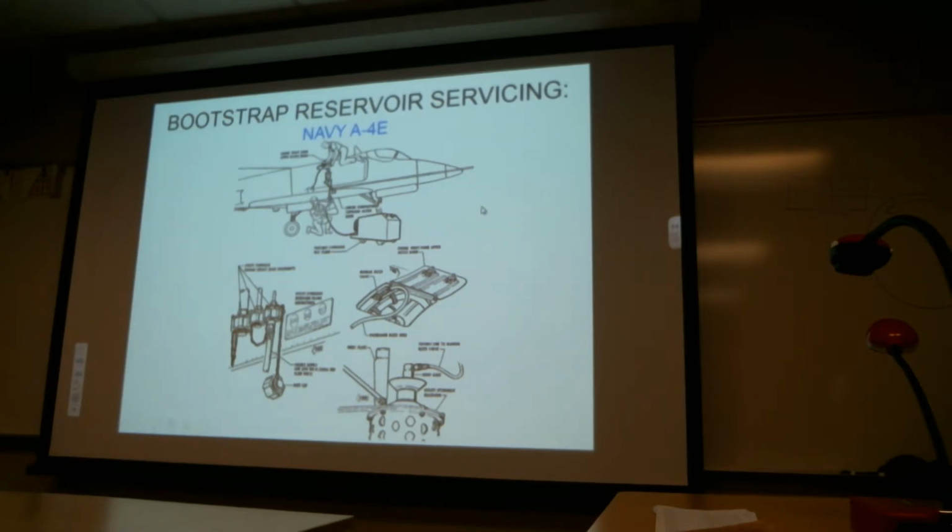Bootstrap reservoir servicing is kind of a problem. Again, you're going to have to service under pressure. They don't have a cap on the reservoir that provides for adding fluid. What you have to do in servicing a bootstrap reservoir is push the piston back in the reservoir in order to fill it back up again. Sometimes even that bootstrap reservoir will have a spring in it that provides for the initial push on the fluid. So you have to have something that overcomes the spring on one side of the piston in order to fill it back up again.